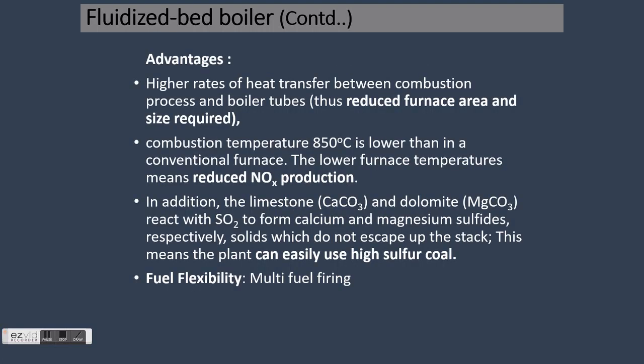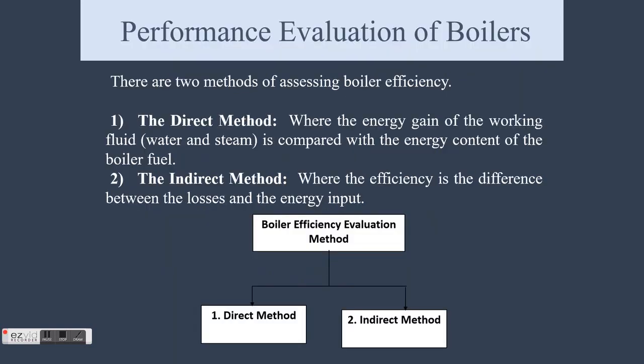Next, a very important topic is performance evaluation of boilers. The performance parameters of a boiler, like efficiency and evaporation ratio, reduce with time due to poor combustion, heat transfer, surface fouling, and poor operation and maintenance. Even for a new boiler, reasons such as deteriorating fuel quality, water quality, etc. can result in poor boiler performance. Boiler efficiency tests help us to find out the deviation of boiler efficiency from the best efficiency and target problem areas for corrective action.